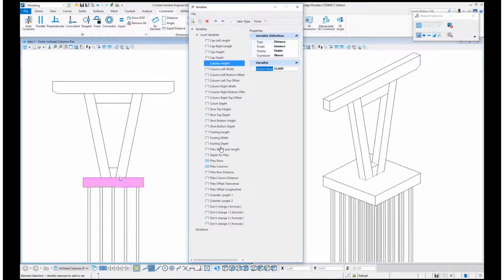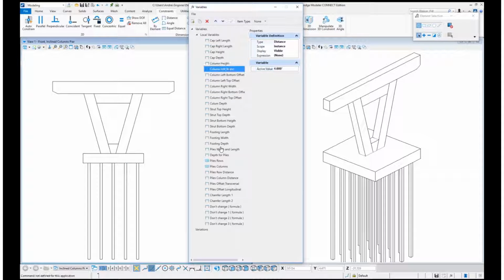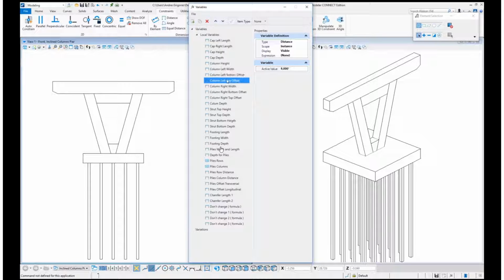You cannot mix and match with the tools that we have. You cannot say, oh, I do the piers parametric, and then the piles I will use the dialog box. It doesn't work that way. You have to define the entire pier structure with a parametric cell if you want to do that. You cannot mix and match the tools.